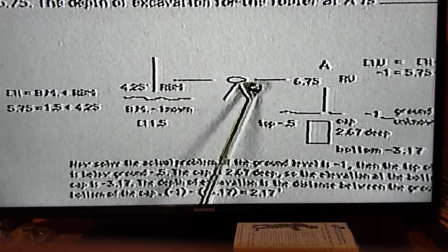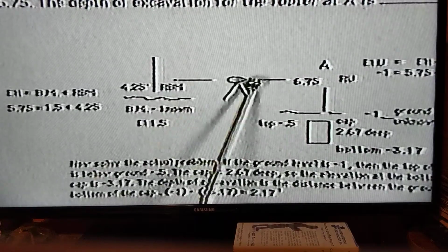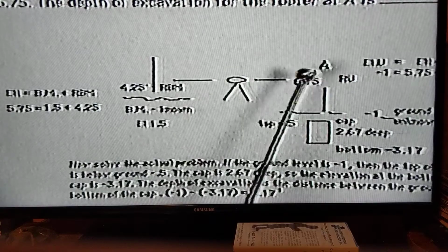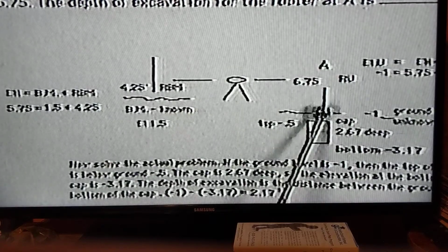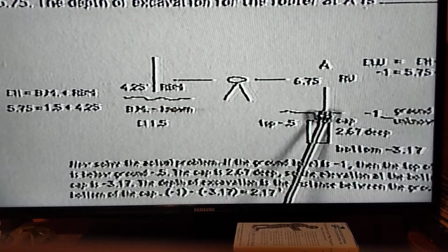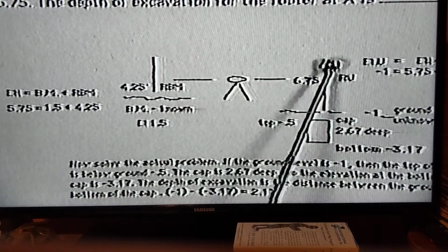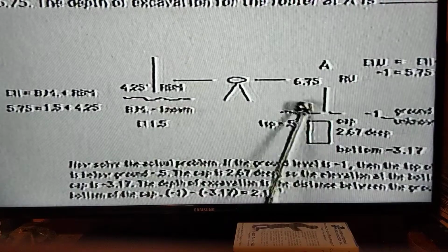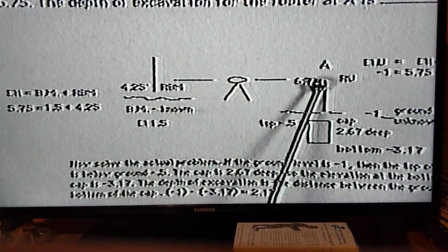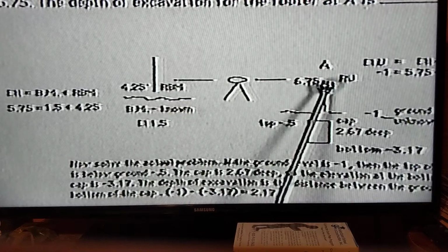Well, for example, if you knew for sure that this line of sight had an elevation of, say, 10, and when you looked in the direction of your own unknown elevation and you put a rod on top of that unknown elevation and looked to see what number you would see, and the rod would be marked with 1, 2, 3, etc. And let's say when you looked through here you saw a 5.